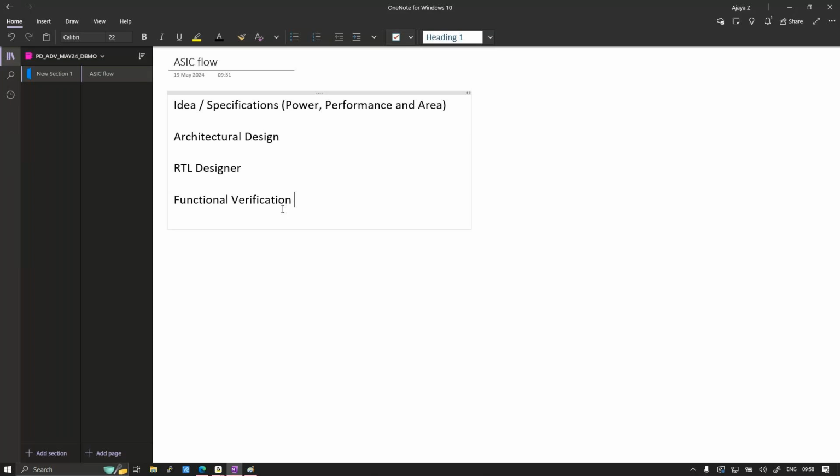This particular person is initially going to be testing whether that particular requirement is followed properly or not. So only that particular check, by using test bench codes, or let's say now it's advanced. Writing test benches is a hectic process. So that has been developed into different languages. Okay, UVM, and also there are different tools to support it. So by using those tools, they are going to do this functional verification.